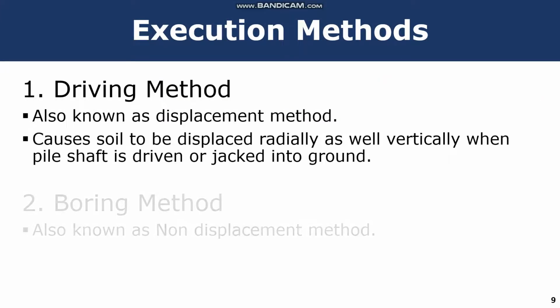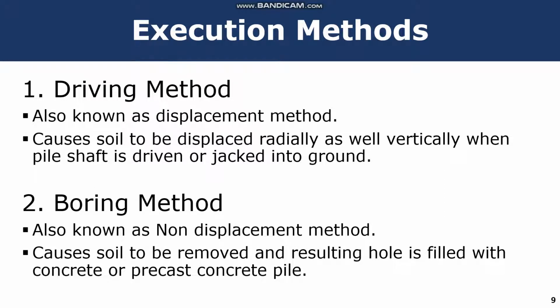So, execution methods. When we come towards the execution, there are two methods. In the driving method, we basically utilize force to drive the pile inside the soil, and when we utilize that force, it causes displacement of the soil, and the pile will try to make its way through that soil. When we talk about the boring method, we are actually removing the soil and then putting the pile inside that earth, because there is a hollow volume available for us to put a pile inside that hole. So there are two methods: driving method and boring method.